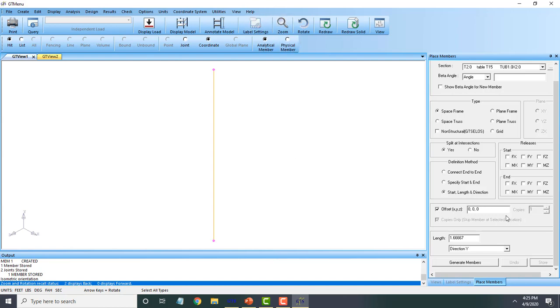Now I'm going to draw my second member. For that, I'm just going to go in and say joints, because now we have joints. We can draw our additional members relative to this member that we've created. And I'm going to say I want to place a similar member at a distance of, now this box has a unit converter, so I can type in 2 feet and 8 inches, and it'll convert it to decimals automatically if you press tab.